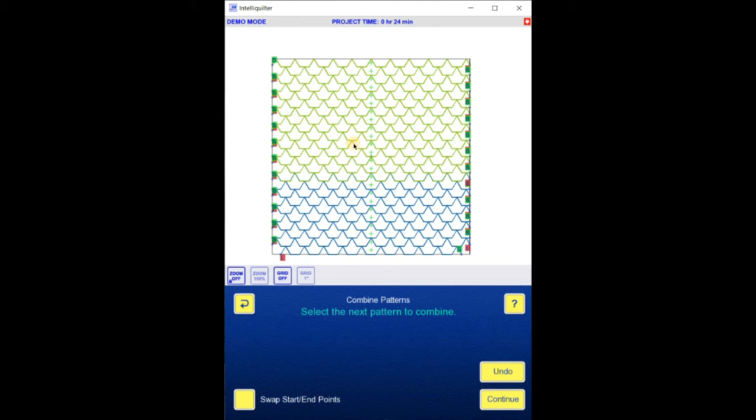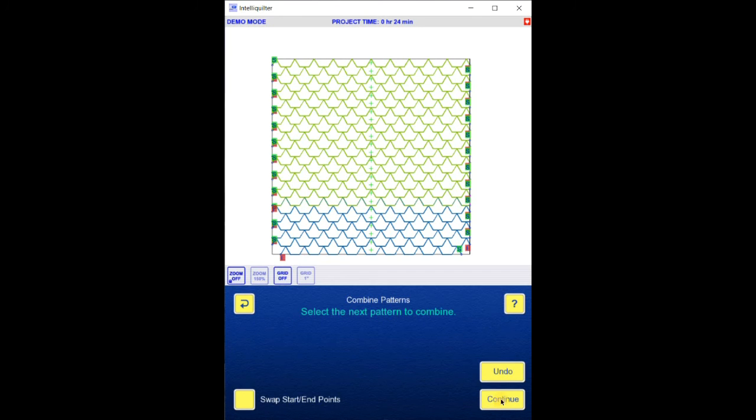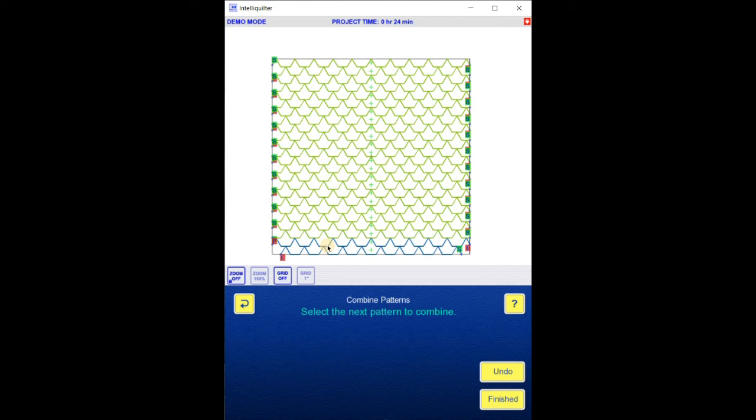So you're going to want to make sure your block is big enough. In this case, I wanted my shingles half this size. So let's say I wanted to fill a 6-inch space. I want to make sure my block was at least 12 inches. It's always better to have it bigger than smaller. I think I said I wanted my shingles 1/2 inch, and that's what they are, but I meant I wanted them half this scale. So this is as small as I could go with the pantograph.